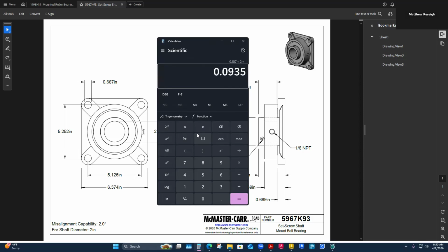The other thing I like about having that drastic step between the two is that a 7/16 and a 1/2 inch are really close. Just looking at them on a table with a bunch of fasteners, it would be harder to pick the difference between a 7/16 and a 1/2 inch fastener. It would be hard to make a mistake assembling this if one side has 5/8 and the other side has 7/16. You can't even mix those two up. They're drastically different from each other. So that's kind of nice in some ways,